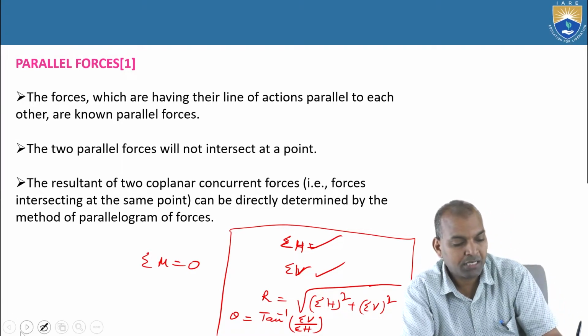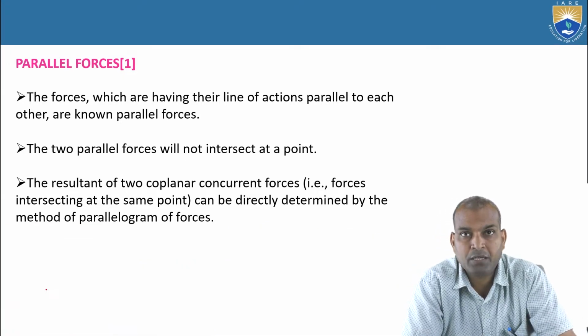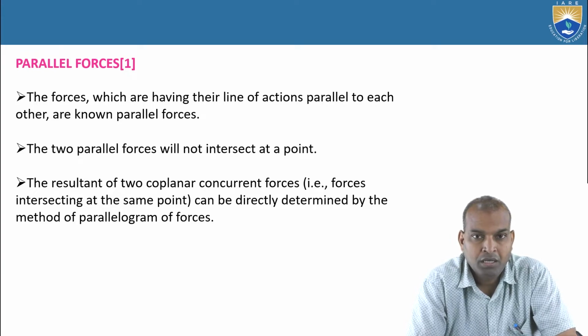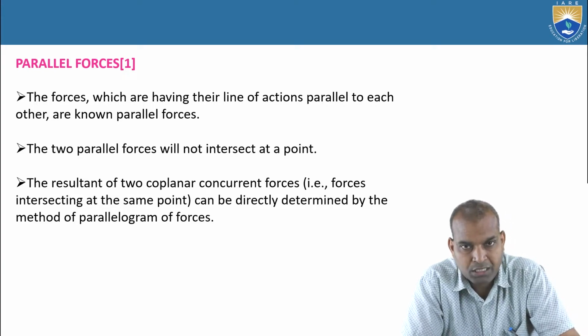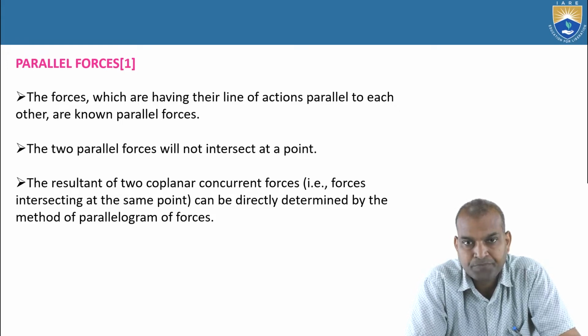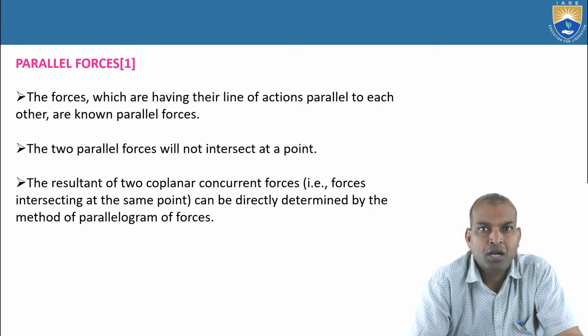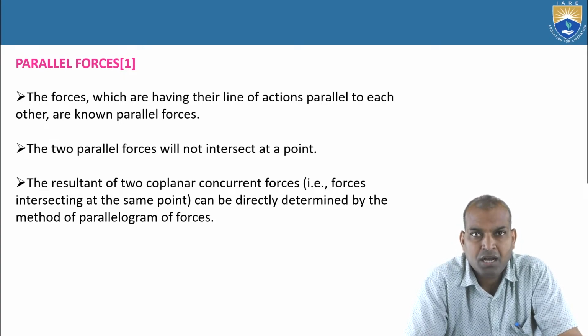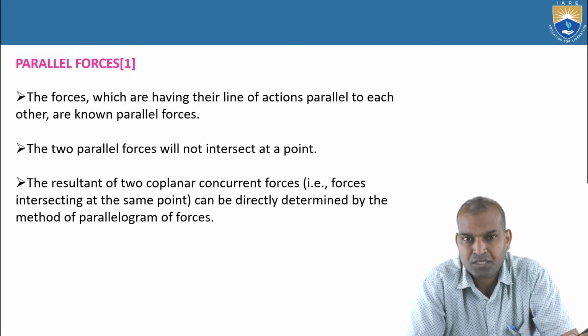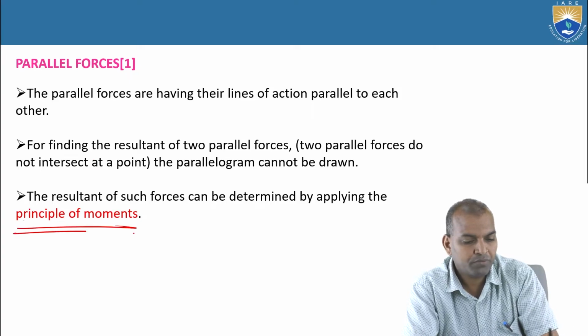Now coming to the concept of coplanar parallel forces. What are coplanar parallel forces? A number of forces act, and their directions are parallel to each other, so they don't intersect at one point. Each force meets the body at various points. That is the meaning. Now, how do we find the resultant of such forces? By using the law of moments, the principle of moments.